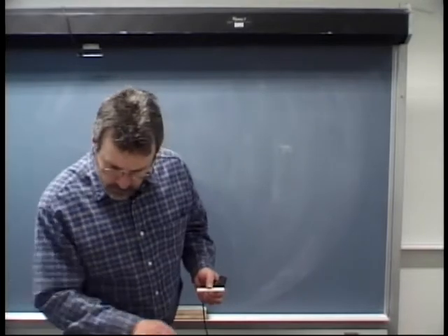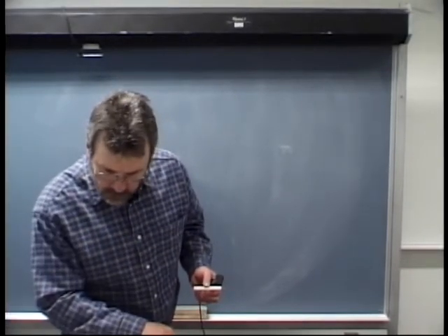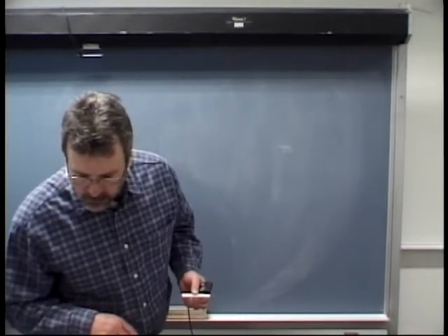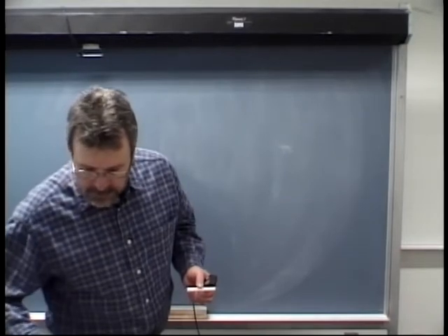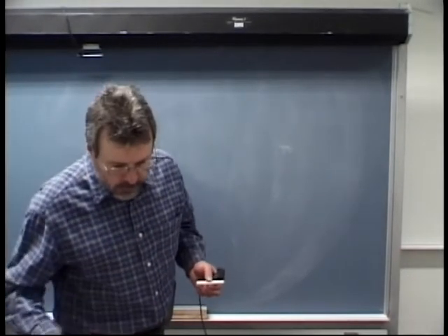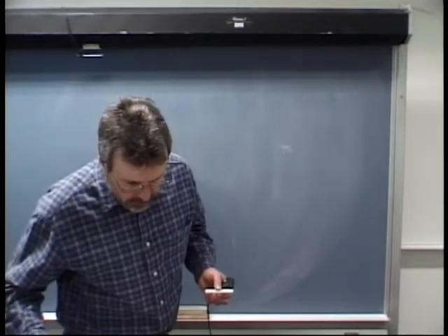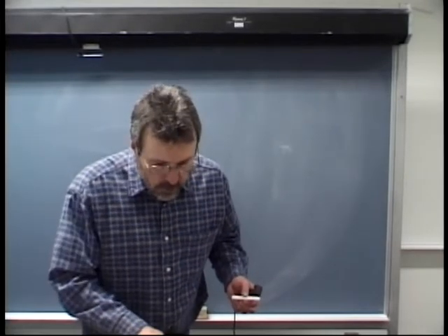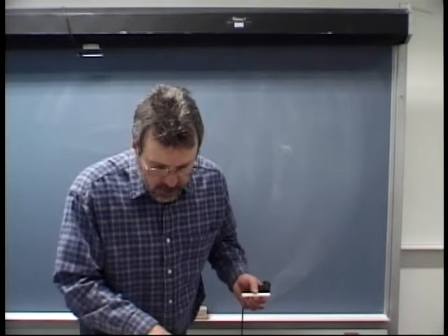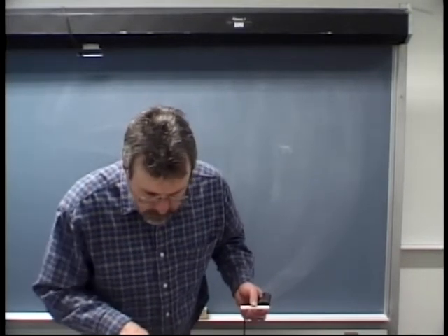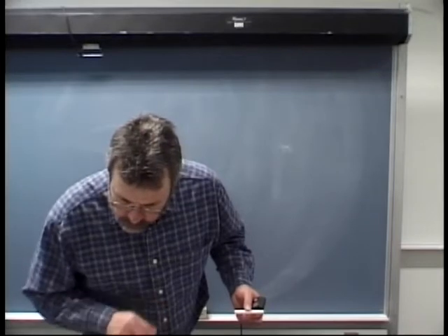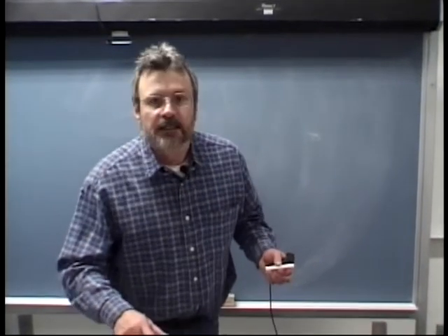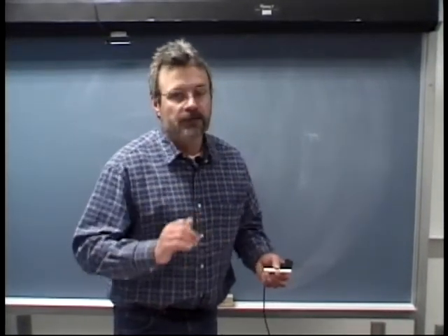If you'll flip back to figure 30-3 on page 1105, you can see that a back weld is clear, but a melt-through symbol is darkened. It's colored in. That's how you tell the difference. Also on page 1106, where it says American Welding Society Standard Welding Symbols, you can see the melt-through symbol is darkened in. Whereas on page 1107, you can see the back weld symbol is clear. So know that distinction. They color it in for a reason, okay?